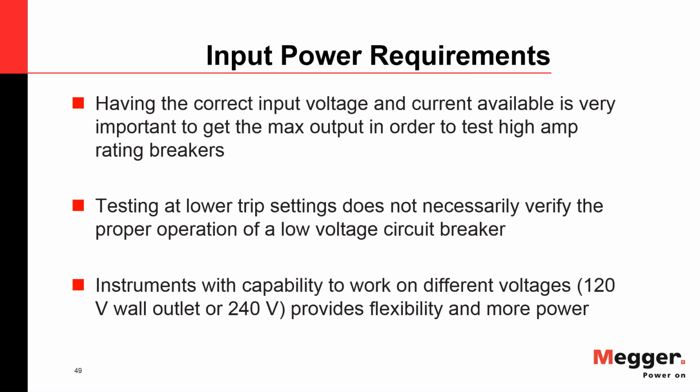So you have to make sure that you keep your voltage drops to the box as low as possible. That's not always possible in the field, I know, but you have to be careful with that at least.